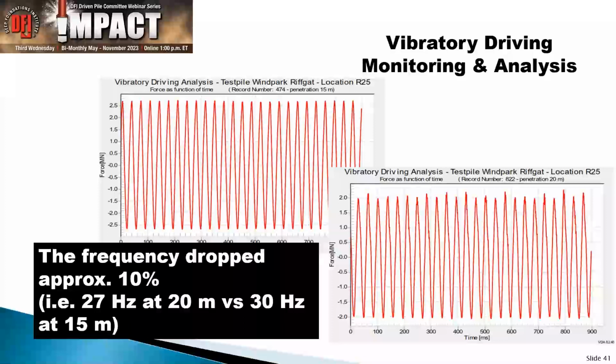You say, well, that's only 10%. Yeah, but the relationship between the frequency and the force is squared. So you go down from 1 to 0.9, or with your force, 1 squared is 1, 0.9 squared is 0.81, and that's where the 80% came from.